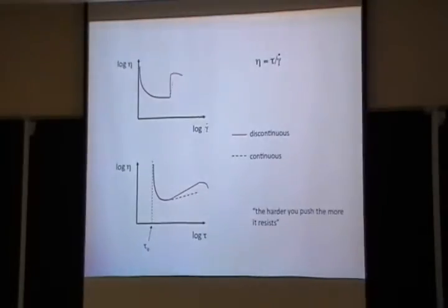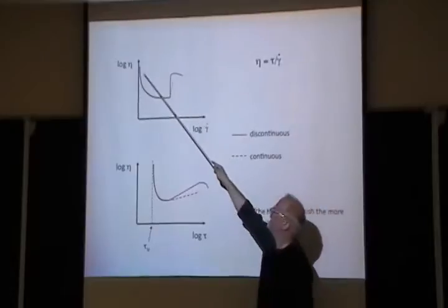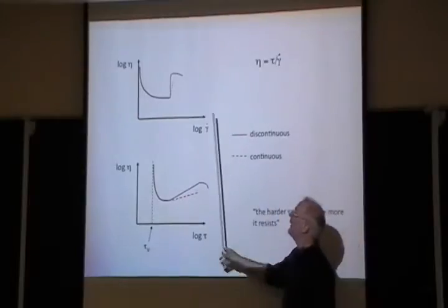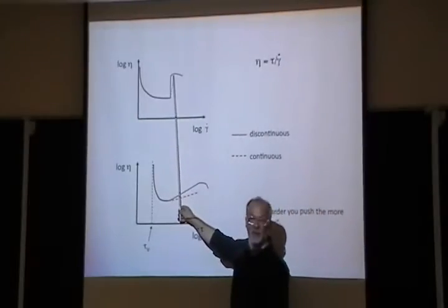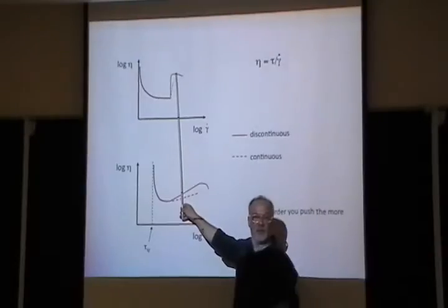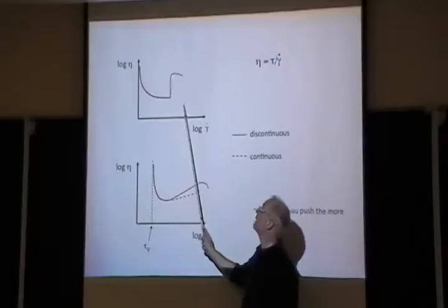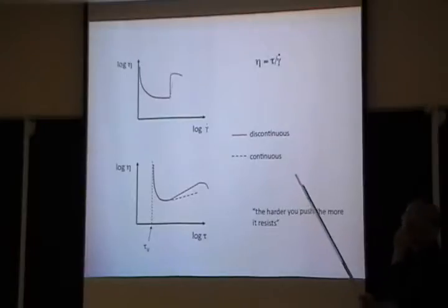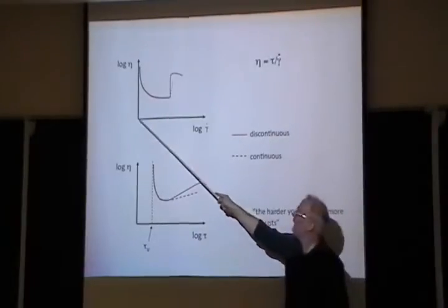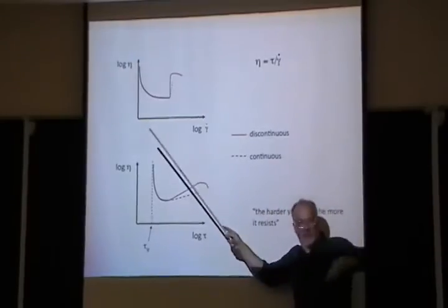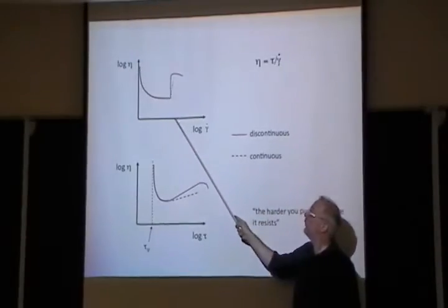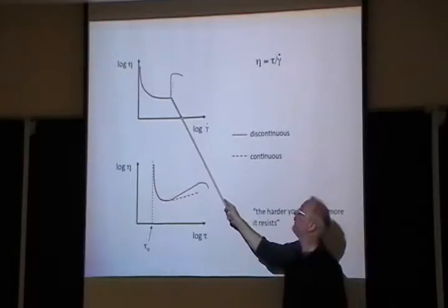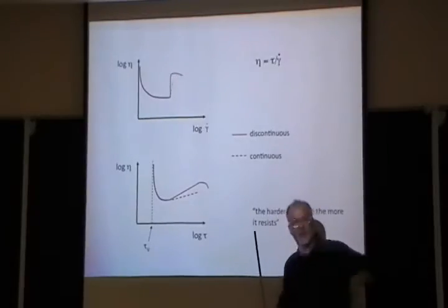Now, in cartoon form, this is what we're dealing with. Okay? Something that comes down and it jumps up. And typically at some point it goes over here. So what that means is that there is a certain shear rate, gamma, where you can have all sorts of shear stresses, and therefore all sorts of viscosity jumps right up here. Right? And so what that basically says is that if you march out here, you increase the rate at which you work, you come to this point and you can't do anything anymore. Your shear rate is not increasing. Your motor is maybe going to die because you would have these enormous stresses. The viscosity gets so high, you can't even churn that liquid anymore, right?